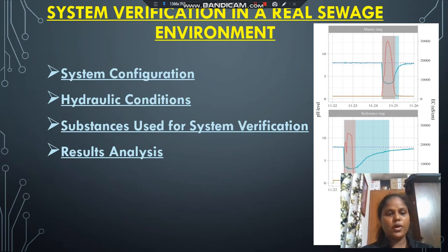A regular check of wastewater composition confirmed that no significant amount of rainwater or groundwater had penetrated the connected sewer during the test. Next are the hydraulic conditions. During the test, the water level, the flow rate and the velocity could be adjusted in order to simulate hydraulic conditions that are typical for a municipal sewer system. By adjusting flow rate and velocity, dilution of the discharged substance and flow time between our IoT devices could be varied. Flow rate and velocity of the sewage were adjusted by regulating the frequency of the pump according to the values given in the IoT systems.